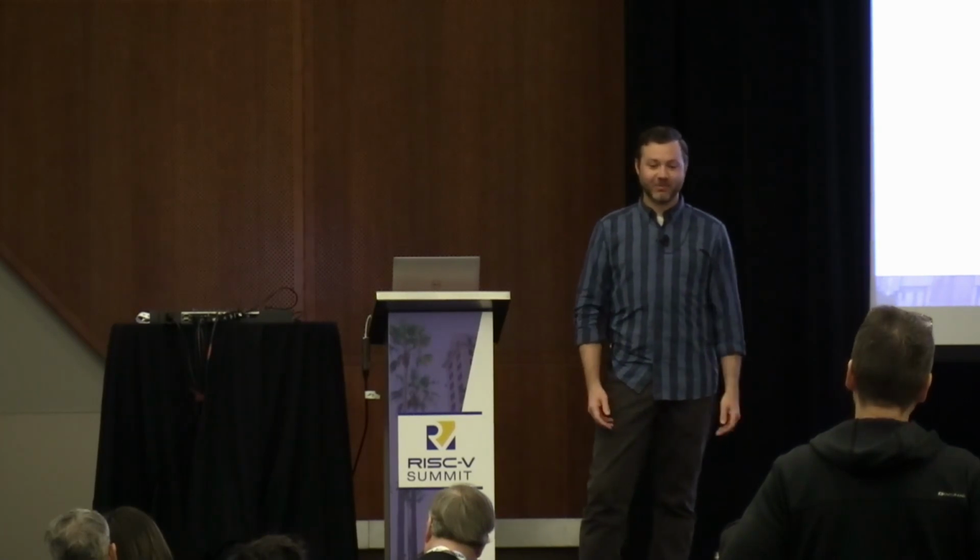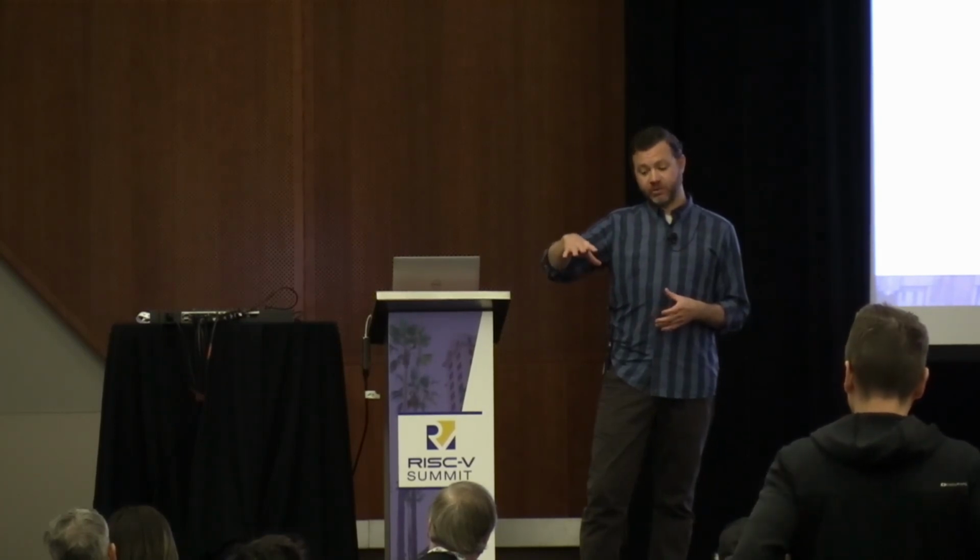So yes. When you're building or designing a system, you obviously want to match that. And so if we are going to mandate some of the page sizes in a profile, then likewise, when you build out a platform, you would want to have a similar mandatory page size on all IOMMUs in the system.